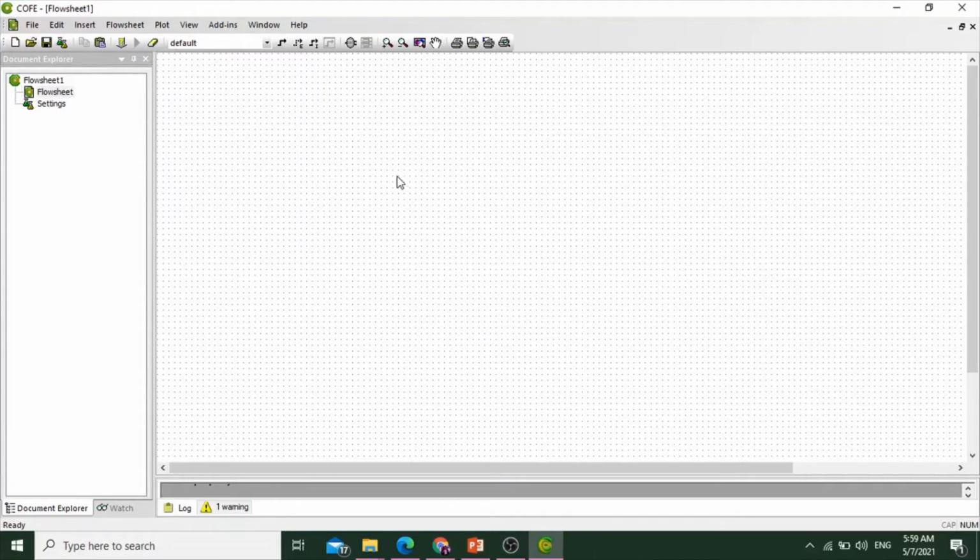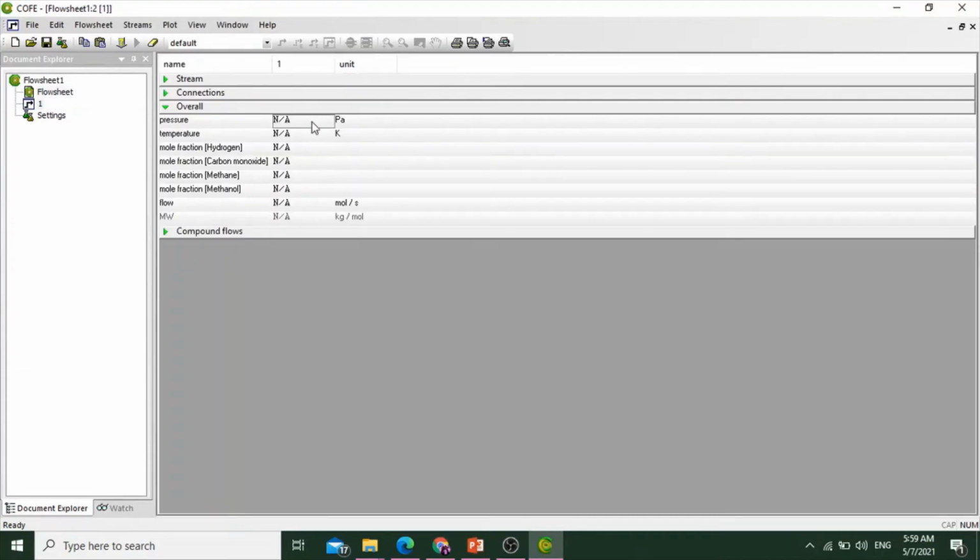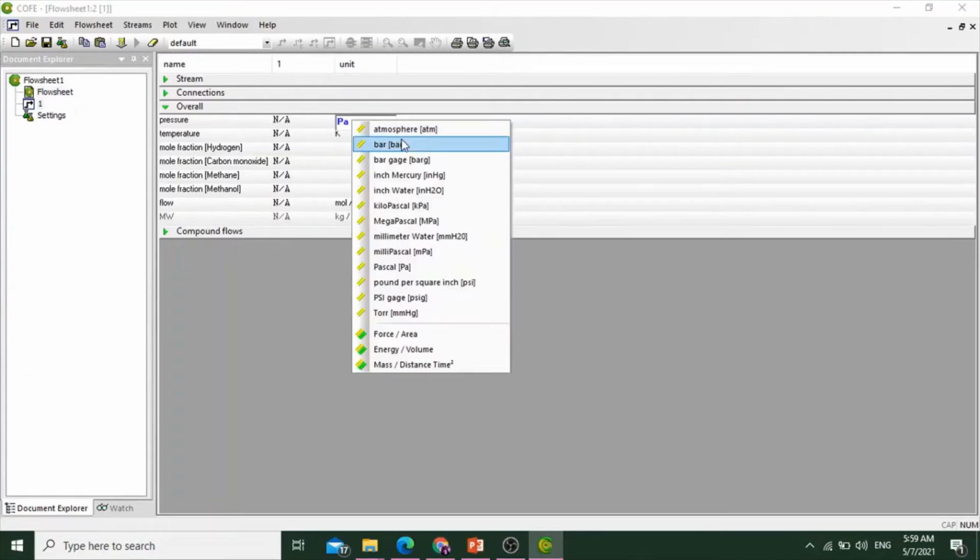After having the flow sheet, we will insert a stream. Okay, this is stream number 1. We will add values in stream number 1. We'll have a pressure, and its units in system international will be kilopascal.